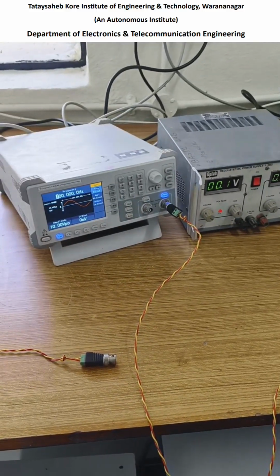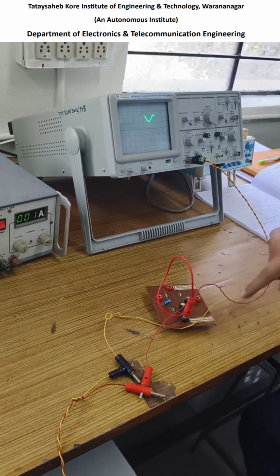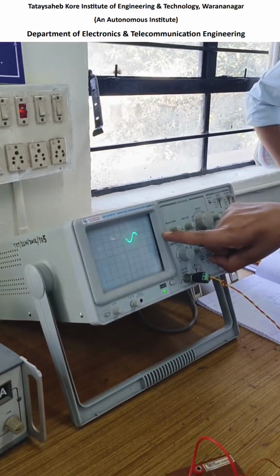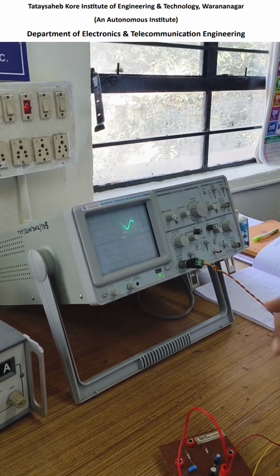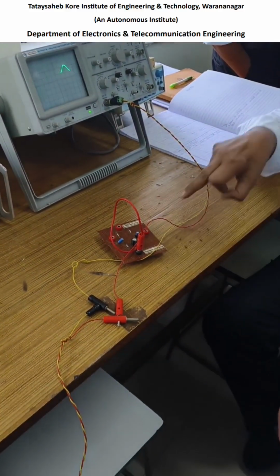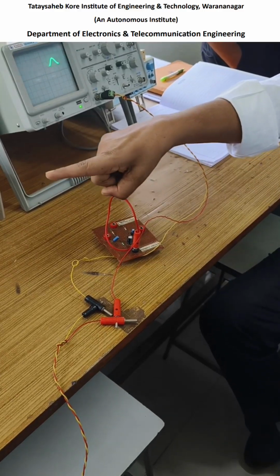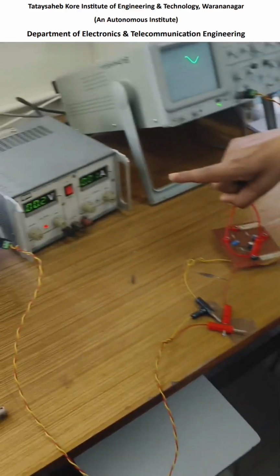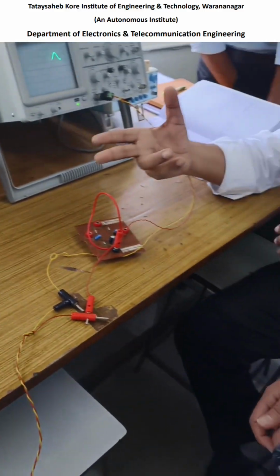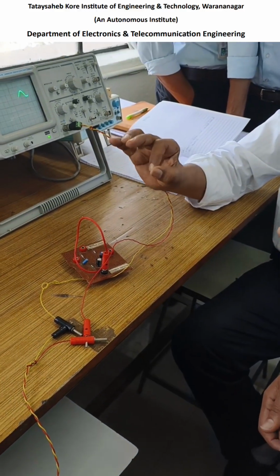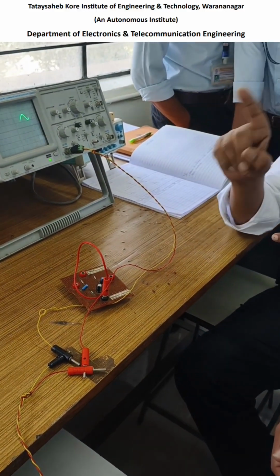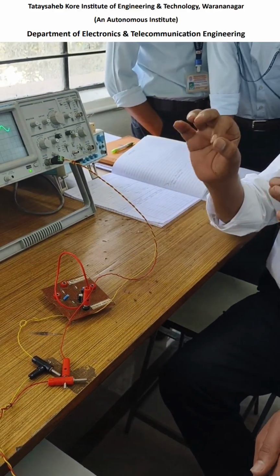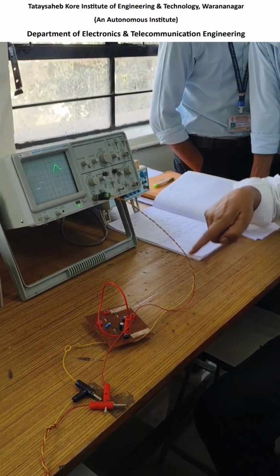So keep in mind, after connecting also if the signal is not there on the screen, you have to take care to check the connection of the probe with the output terminal. Now the button which you pressed will glow showing the blue light. It indicates that not only is your signal generator on, but simultaneously the output terminal is also turned on.